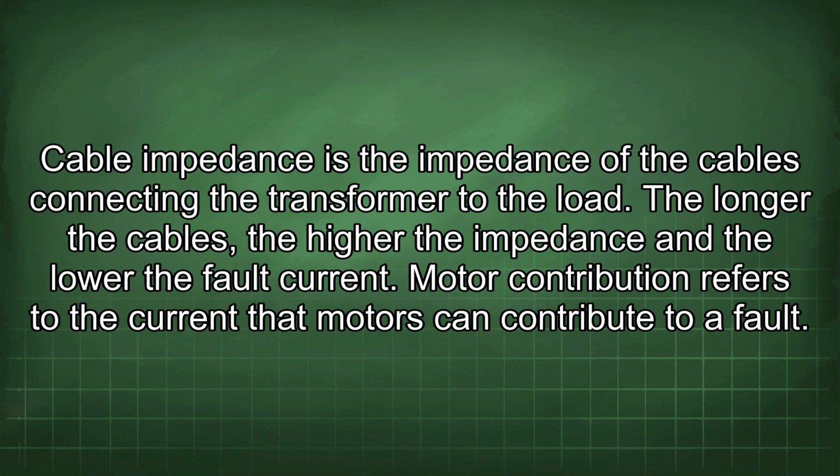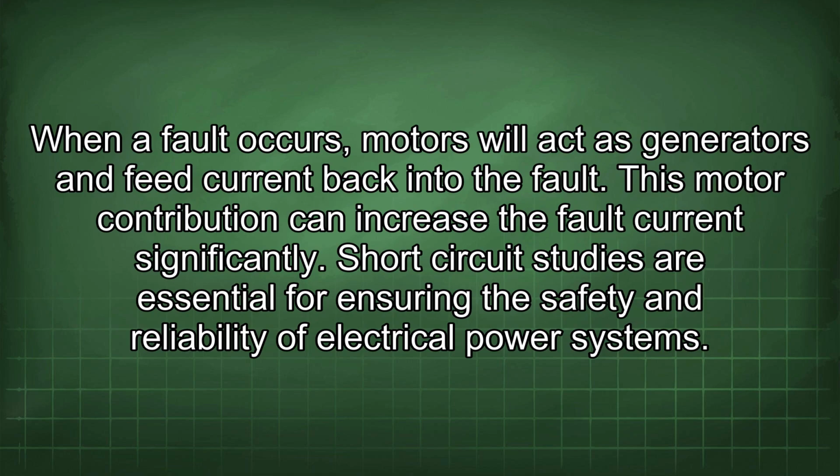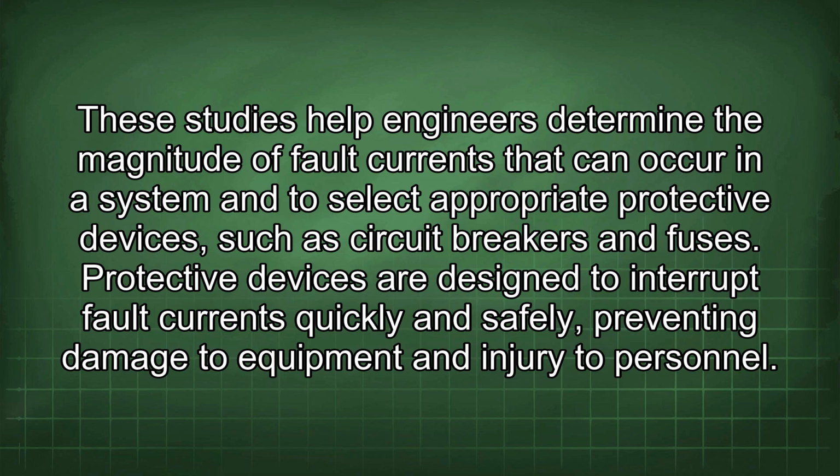Motor contribution refers to the current that motors can contribute to a fault. When a fault occurs, motors will act as generators and feed current back into the fault. This motor contribution can increase the fault current significantly. Short circuit studies are essential for ensuring the safety and reliability of electrical power systems. These studies help engineers determine the magnitude of fault currents that can occur in a system and to select appropriate protective devices such as circuit breakers and fuses.